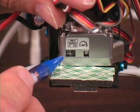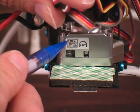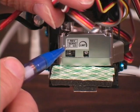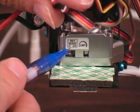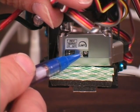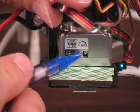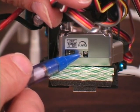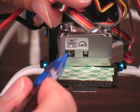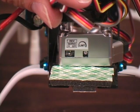Here are these itty-bitty little pots. The top one sets the reverse of the gyro. That's the one we want to move. The bottom one, when the switch is to the left, it's for a high-speed digital servo. When the switch is to the right, it's for a normal servo. And here's the limit pot. We want to make sure the limit pot is wide open because we'll set the pirouette rate by where the push rod is in or out on the tail rotor servo. So to reverse the direction of the gyro, all that I have to do is move the top switch over to the right.